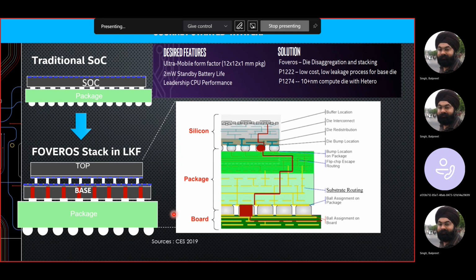So if you think about the good questions you raised about the power delivery, you see the same stuff. I just put it in a little magnifying glass. It comes from the base die. This is typically the package side pin or a package ball, whatever you call it. It goes to the package, through the base die, then to the compute die to the micro bump. So this extra electrical path, from here to here, is going to cost extra voltage drop.